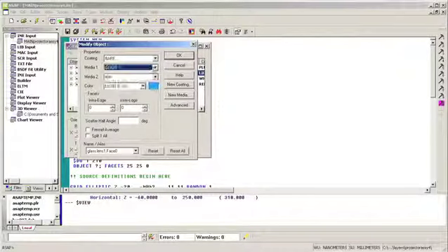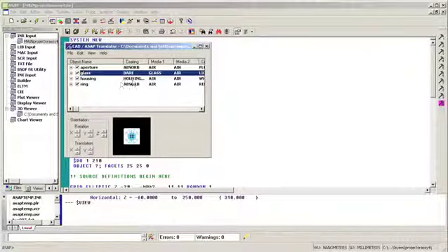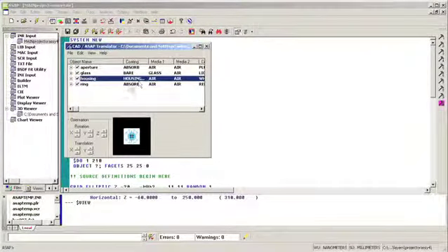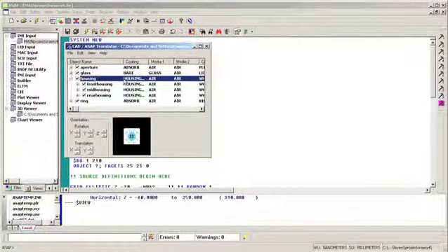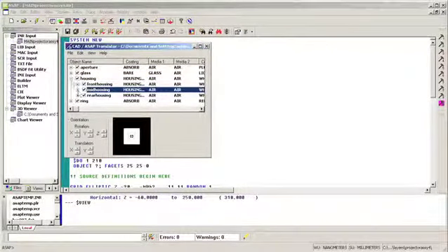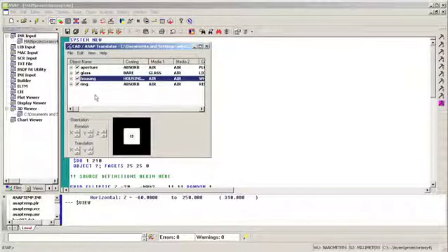Here's glass-air interface. I've given it a color of light blue. So I can go on down the line and assign these different properties to the different layers. And notice how they're retained as well for the expanded tree. So I don't have to do it for each piece. Okay, so when I'm happy with that, I just hit return.